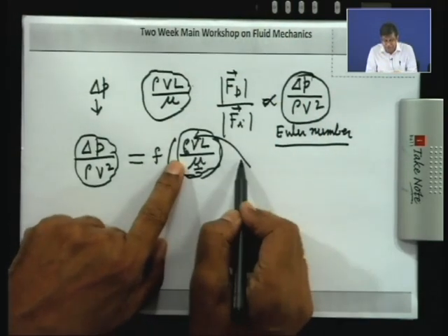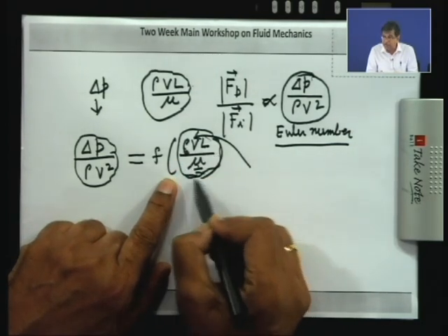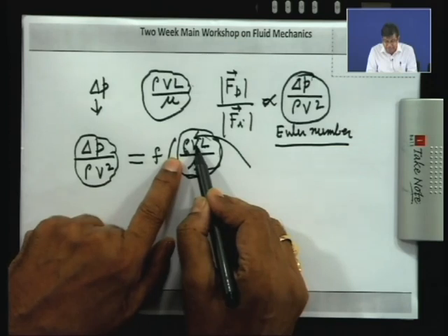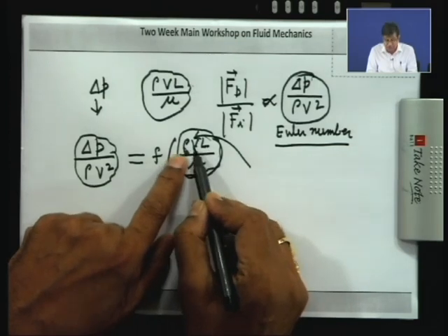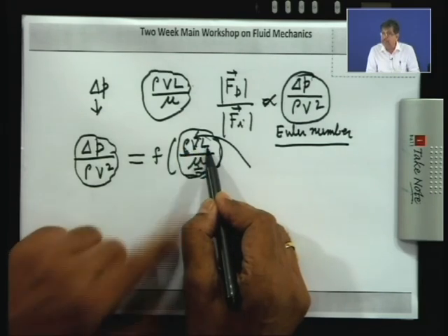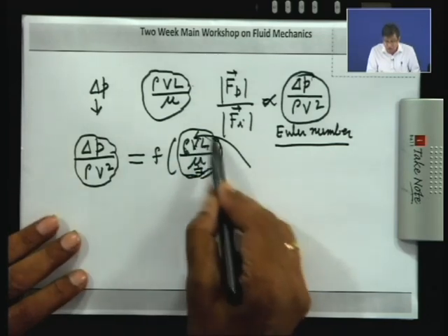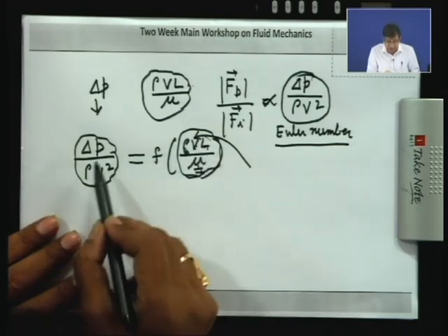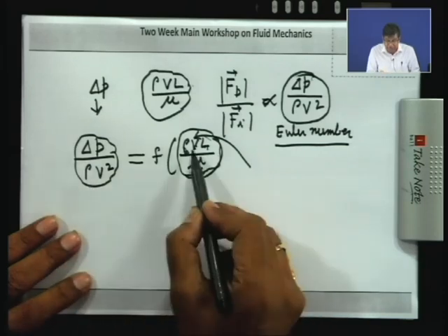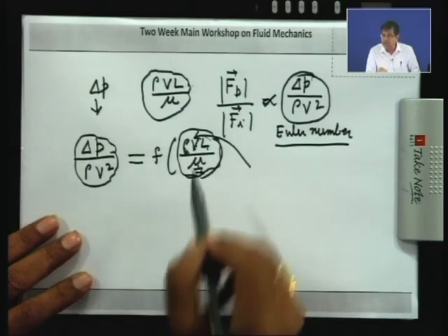By varying the velocity V, we can predict the influence of this combined parameter, which means indirectly varying the other parameters. That means making the velocity double has the same influence as making the length double or making the viscosity half. That means if the group as a whole has an influence, I can change any variable and find out the influence of other variables.